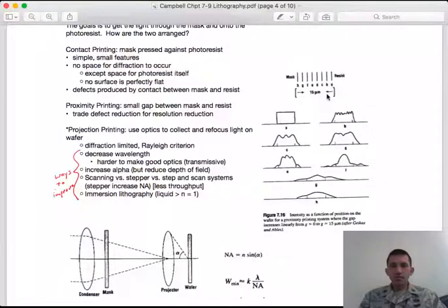So at A, that would be 0, and I ostensibly get perfect transfer. This would be the contact printing case. However, I could anticipate having higher defect densities. As I increase the gap, say in steps of, I don't know, probably a few microns, I start to see the distortion. So my transition broadens. I see distortion along the maximum through the center of the feature. And as I go to greater and greater distances, I'm smearing out that intensity